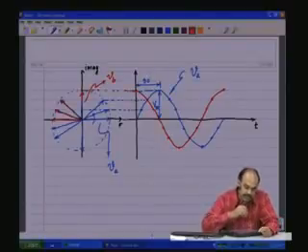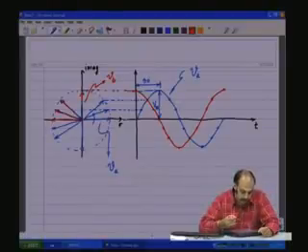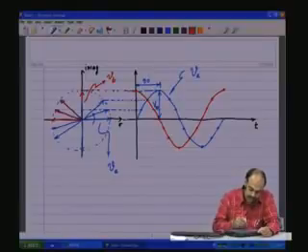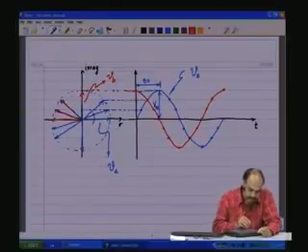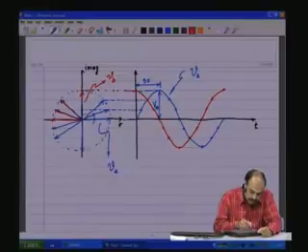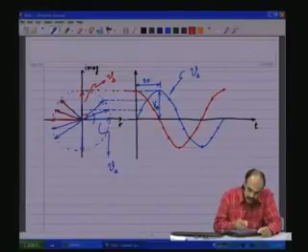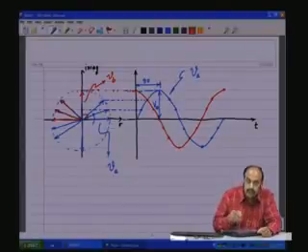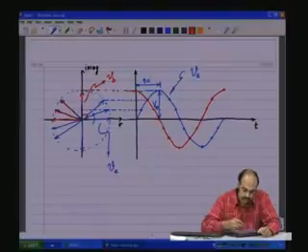So, if I have a space vector starting 90 degrees away from the VA space vector, let us say I have a vector VB which is starting 90 degrees offset or 90 degrees phase shifted with respect to this VA space vector, then you see that the resulting time projection of the space vector tips is a cosine wave.